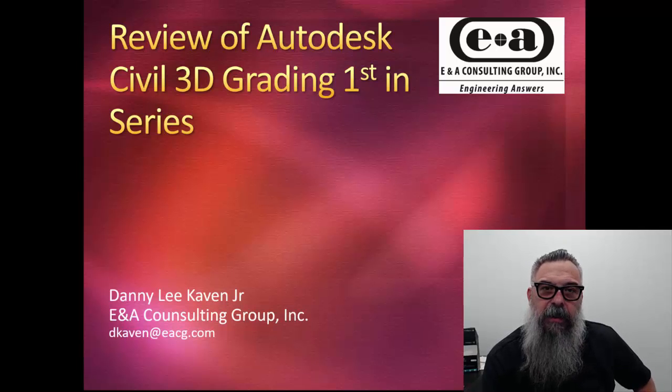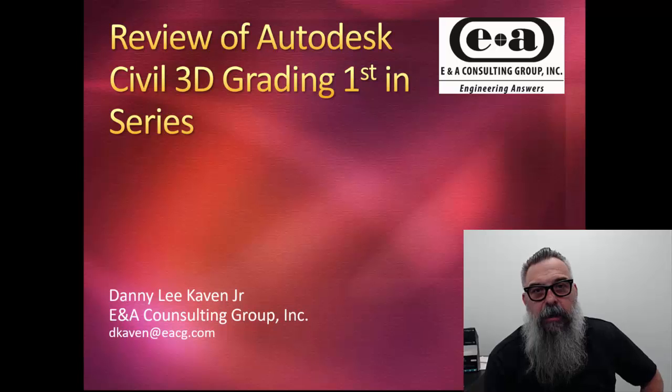Basically, this first series, we're going to start off with working with feature lines. We're going to do a little bit of a feature line in the roadway, show you how to do a grading object and building envelope, and bring that back into the site and push that into the surface as well. We're going to be using grading objects to define back of curb and gutter, things like that.